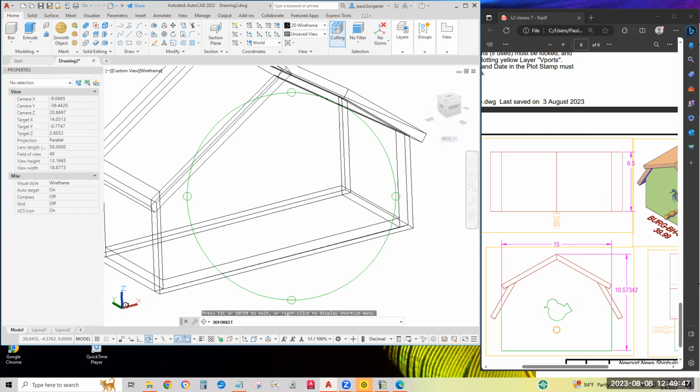Believe we can stay in the World Coordinate System, pick a midpoint in the front, a midpoint in the back, and polar track straight up the z-axis for the third point of the cutting plane. So it'll be a vertical plane right across the center of the floor.